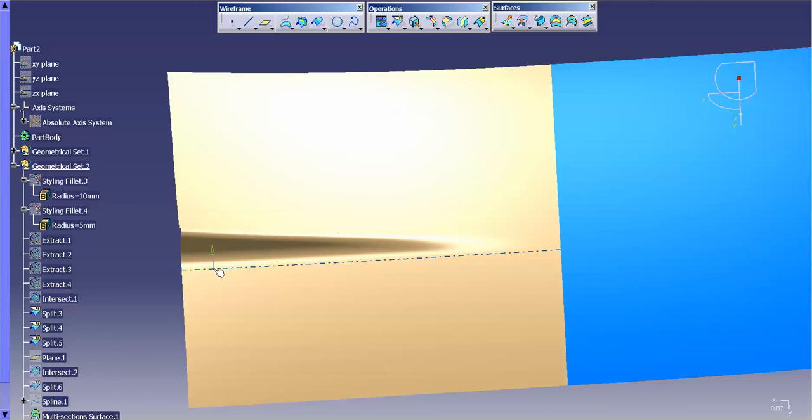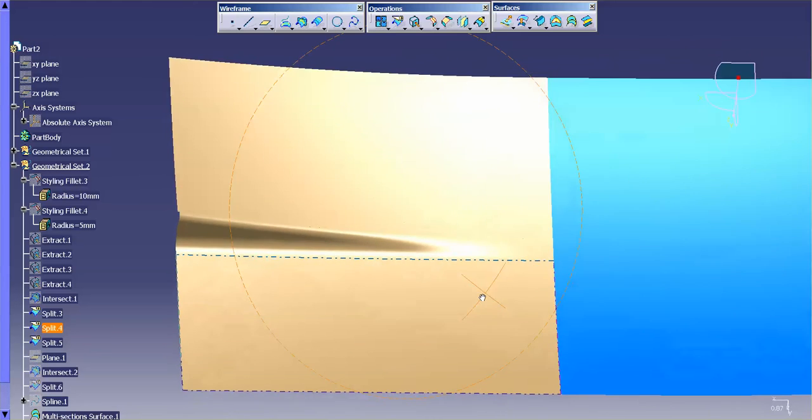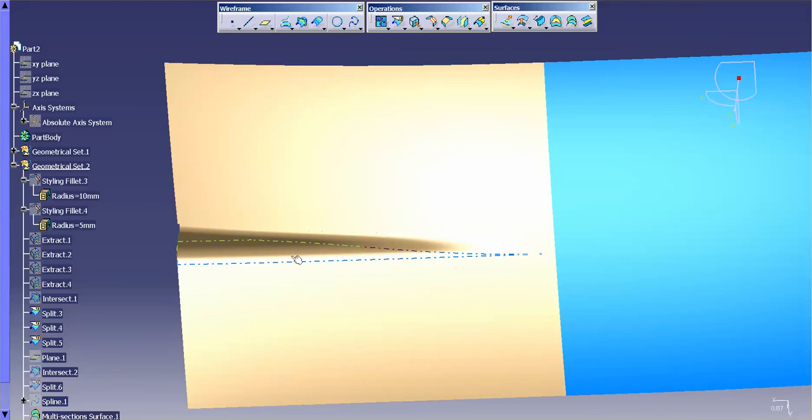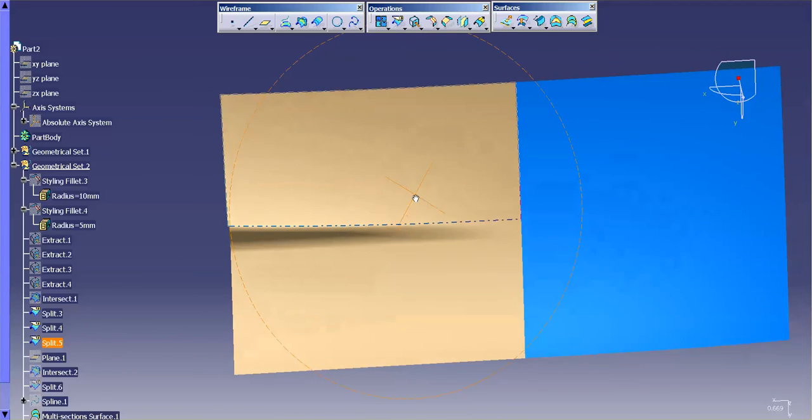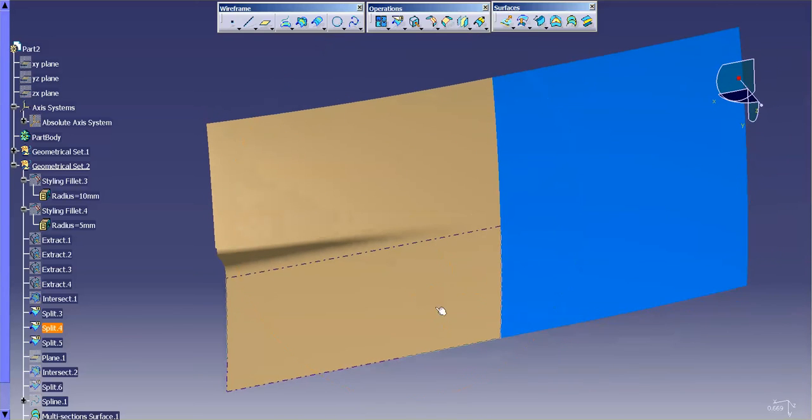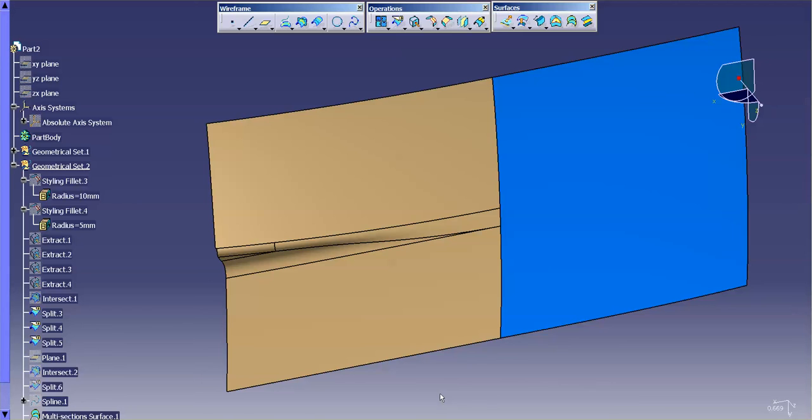You know, some people, like I said, will just simply do a bridge or blend surface from here to here, and away they go. My preference is to actually be able to control that light, control how that flows up and around. And again, you could reverse the order. You could actually have this so it blends out, so this light goes up. And again, depends on what it is you need. So that's a sure, simple way to create transitions that blend off into another edge that are nice and tangent, curvature, and perfectly smooth.